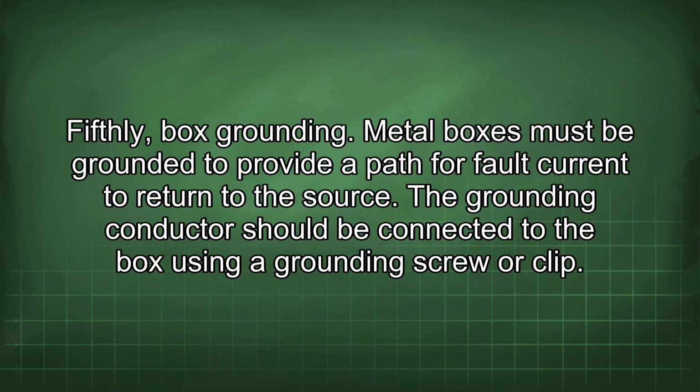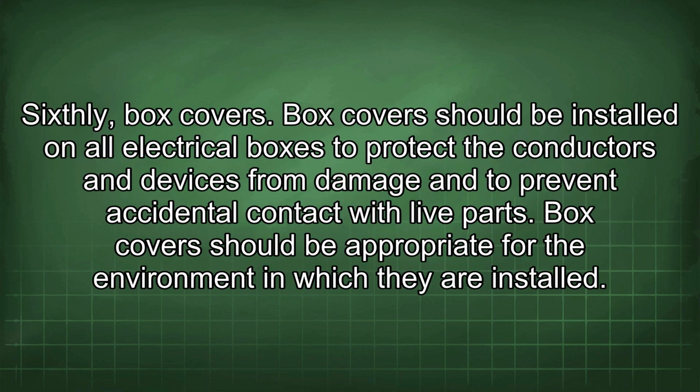Fifthly, box grounding. Metal boxes must be grounded to provide a path for fault current to return to the source. The grounding conductor should be connected to the box using a grounding screw or clip. Sixthly, box covers.